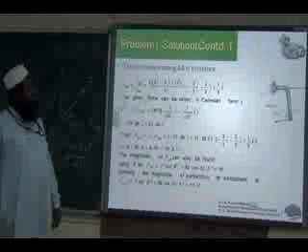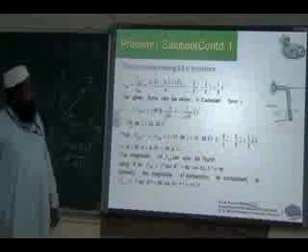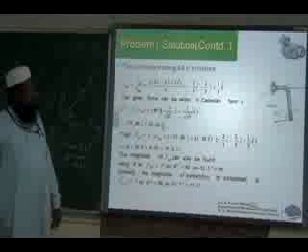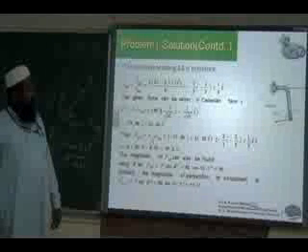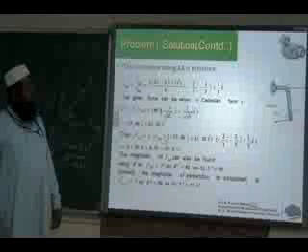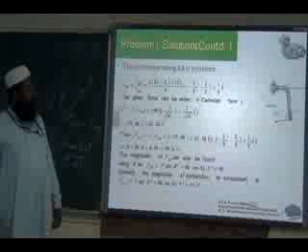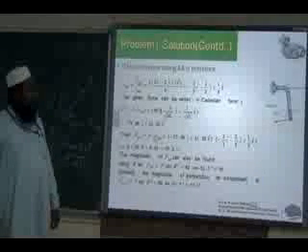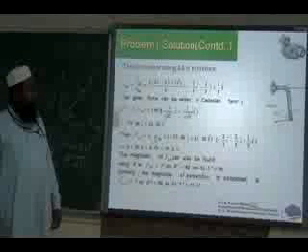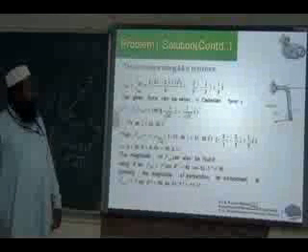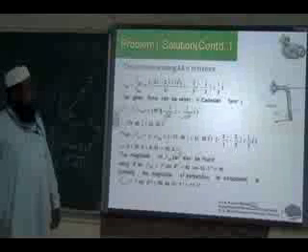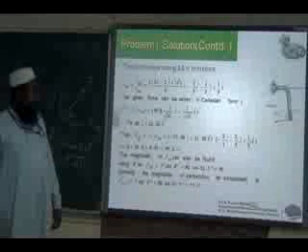The same step is repeated here. So we got the vector along BC. So FPA, we can write F dot UBA, the magnitude dot UBA, for dot products of force F and unit vector BA. So we got the magnitude for FPA.